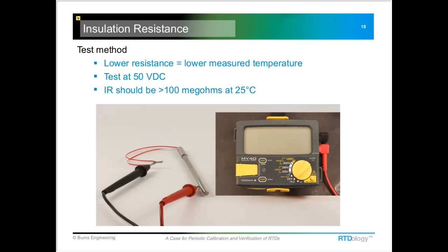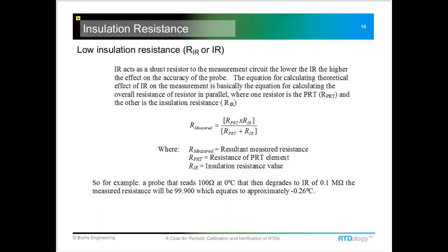At room temperature like this, if you were going to only use a probe at, let's say, 20 degrees C, 70 degrees Fahrenheit, an insulation resistance of maybe 1 megohm is probably all you really need to get a fairly accurate, repeatable measurement.